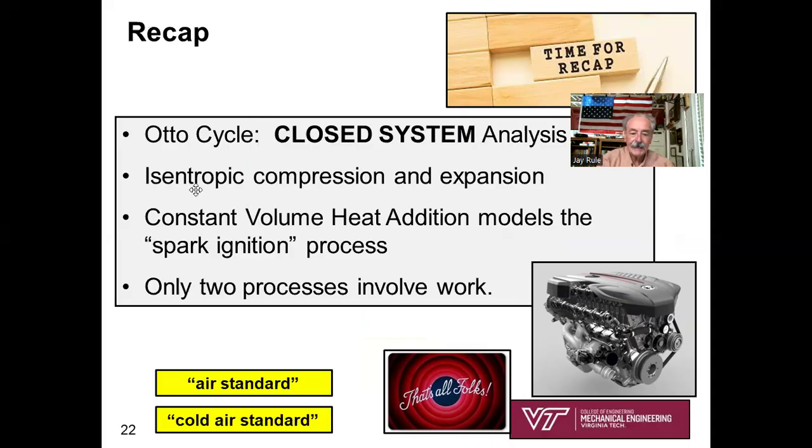Remember, it involves isentropic compression and expansion processes. The heat addition model is instantaneous or constant volume heating that models the spark ignition process. And only 2 of the processes involve work.